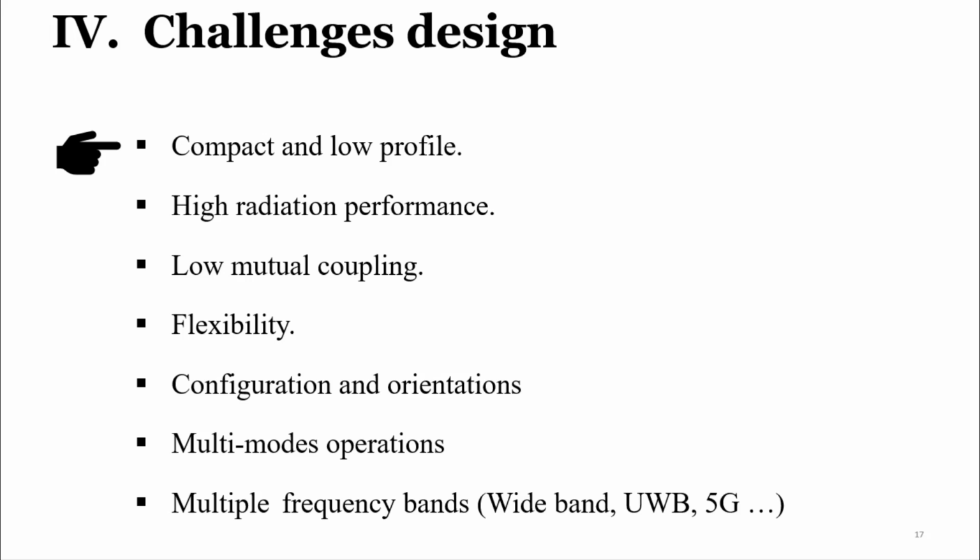Okay, so if I work in C-band, I want to conceive my array antenna for 8 gigahertz. So if I conceive my array antenna at 8 gigahertz, I can obtain a small structure for this band. Okay, so you always need to work with high frequency to obtain miniaturization for your array antennas.